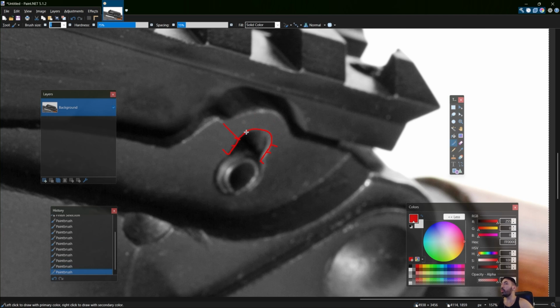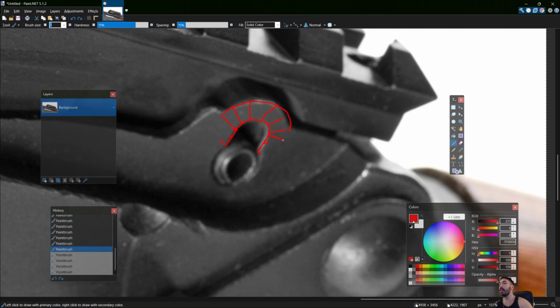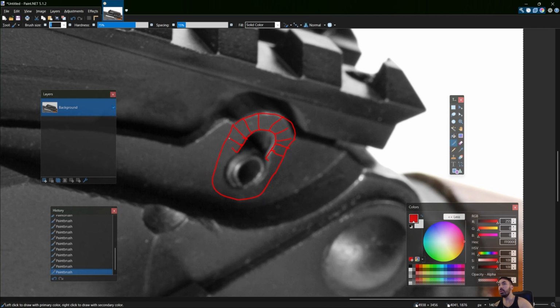I'm thinking we should go with 5 edges or 5 faces on top here, not for any particular reason other than that that is the minimum number of edges that you need in order to create a semicircle which looks nice and smooth under the influence of a subdivision surface modifier, which I do intend to use. Then also, to keep everything nice and clean, I'm definitely going to direct this face loop which flows up here underneath the other part of the hole, which is down here at the bottom. So this is going to be a loop that goes all the way around this hole, and then I'll use the edges from the side here to extrude this little face over here.